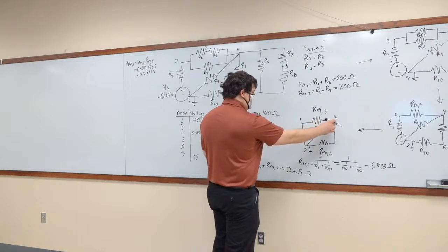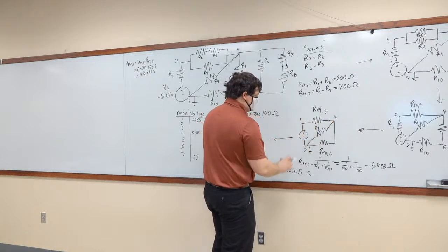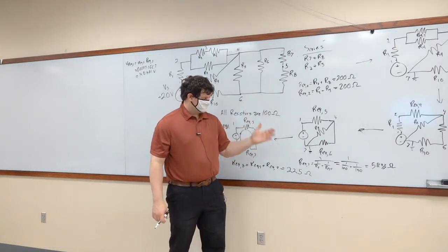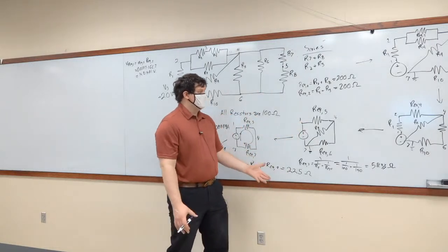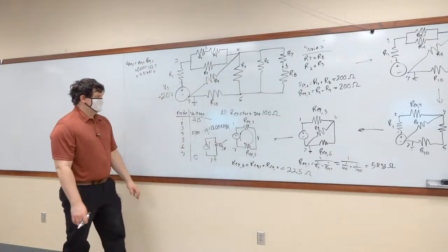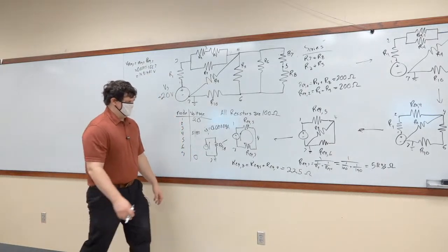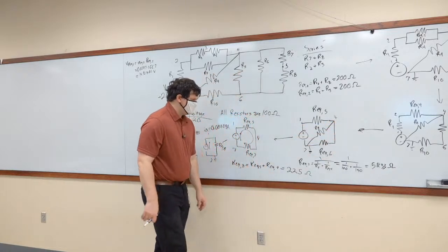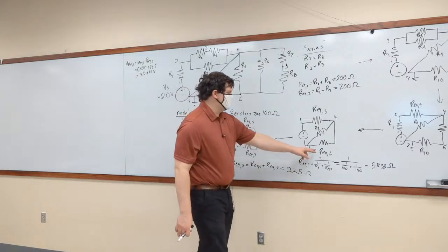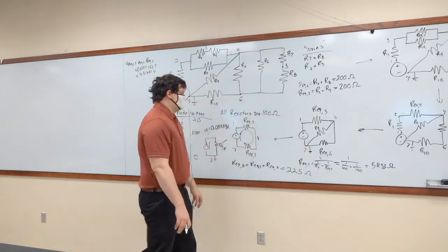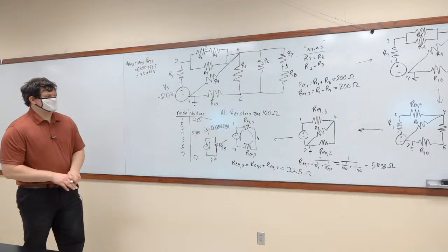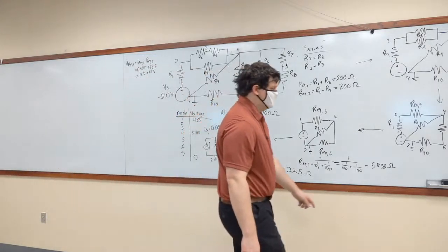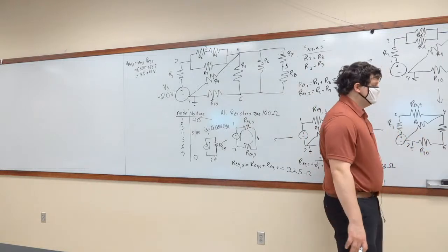It's 0.0888. Because if you do KCL at node 1 over here, it's 0.0888. It has to be equal to the source current. So, plus we already know what the node voltage is at 4. Let's go ahead and find the current through REQ6. Okay? So, REQ6 is equal to 140 ohms.